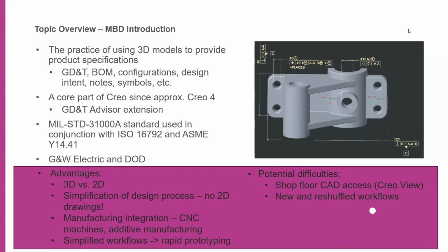There is a standard for model-based definition, but this is going to work in conjunction with ISO and ASME. So your same standards that apply to your current GD&T are likely still going to apply if you do that in model-based definition.